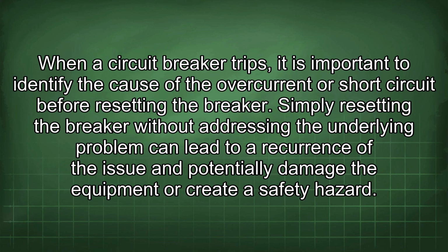When a circuit breaker trips, it is important to identify the cause of the overcurrent or short circuit before resetting the breaker. Simply resetting the breaker without addressing the underlying problem can lead to a recurrence of the issue and potentially damage the equipment or create a safety hazard.